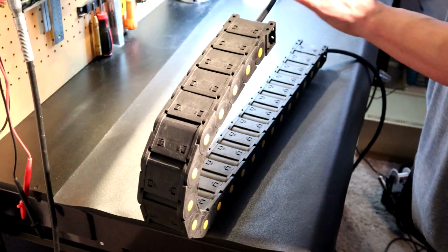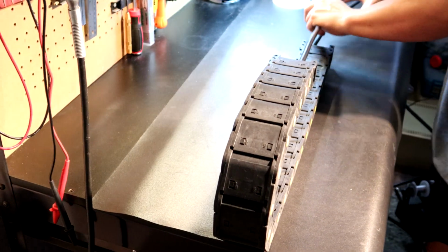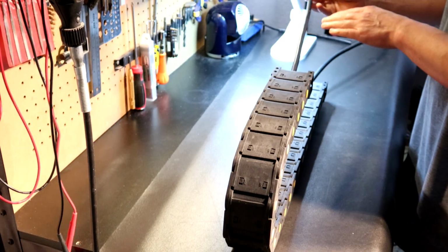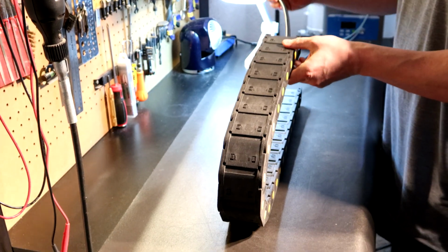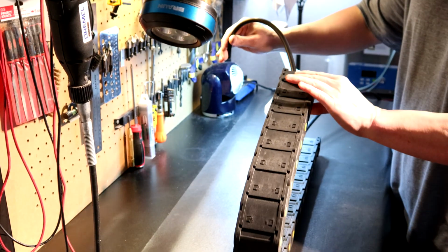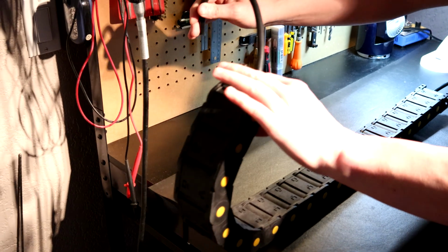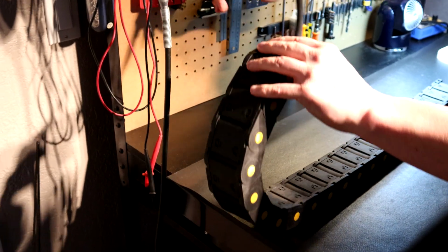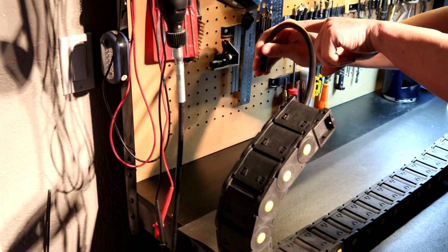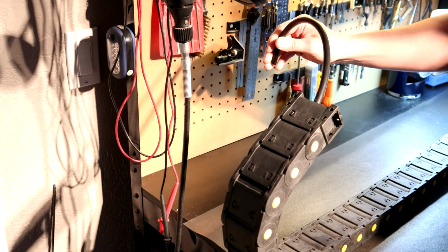The big thing I've seen done, and many of you have seen done, I'm just going to straighten this out a second, is that guys will typically order the shortest cable they can order, and then when they're actually moving on their x-axis, they bend the cable over, and what they forget is when the y-axis comes up, it's going to end up pinching all the way over here, either pinched here or pinched on the other side, depending upon how much pressure is put on the cable, because they're not leaving enough slack in the cable purchase that they make.